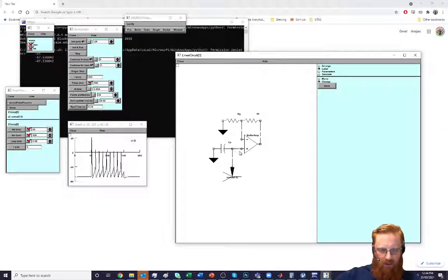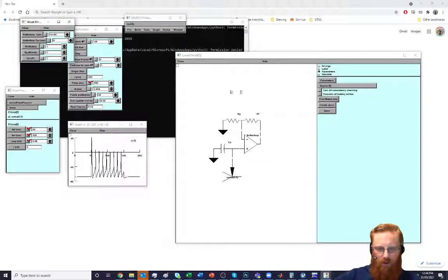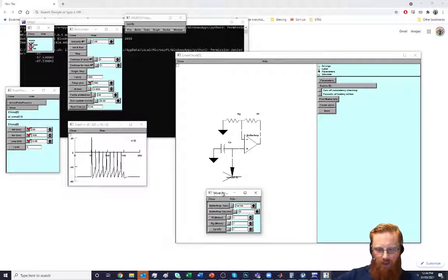And now, of course, anytime the voltage in here changes, there will be a current proportional to the rate of change, which will essentially suck the current out of the cell every time the voltage changes. Now, there's no series resistor and there's no input resistance of the amplifier, so this is not exactly accurate, but it should still work.